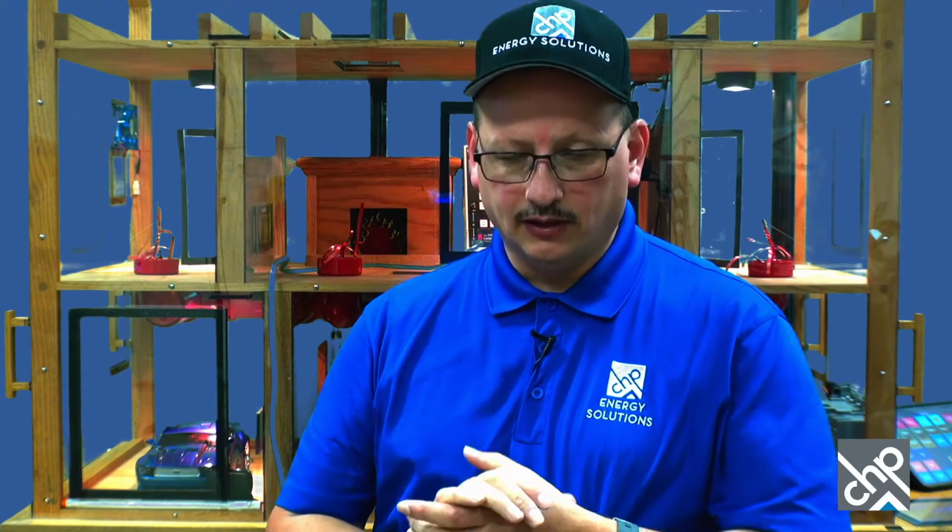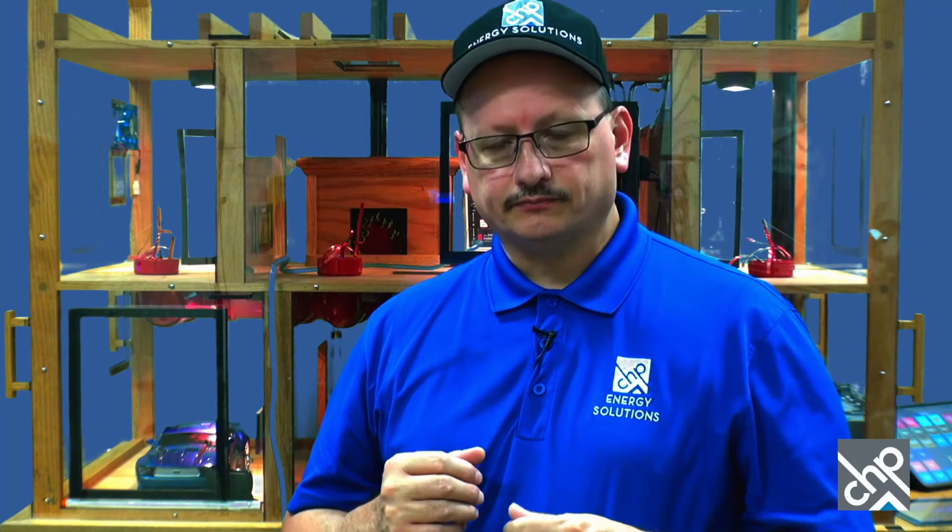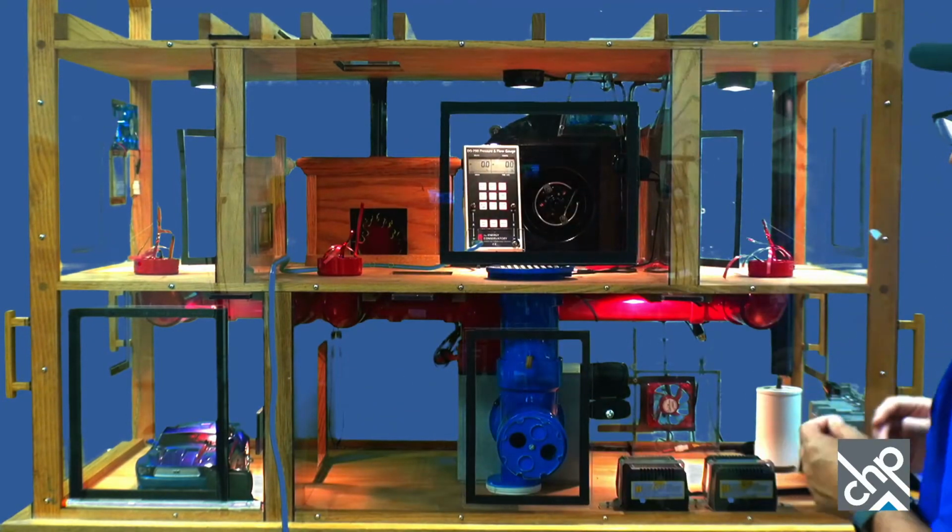The one in the duct, and that's because it's got a furnace fan on there. It's got a higher pressure. The house may leak some when you get windy and stack effect, but the duct system, when it comes on, is pretty much always going to have high pressure, so you're going to have more airflow through that. Plus, like I mentioned before, that's the air you're paying to condition, so you really want to make sure you've got your ducts sealed well. You can do pressure pans. You can do duct testing, similar to a blower door, where you tape off the ducts and test the ducts, that kind of stuff.